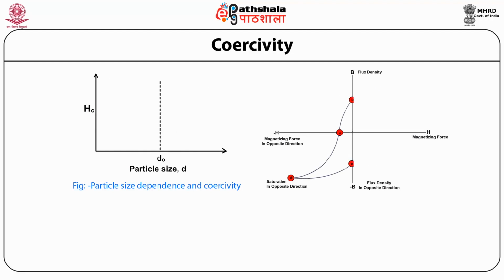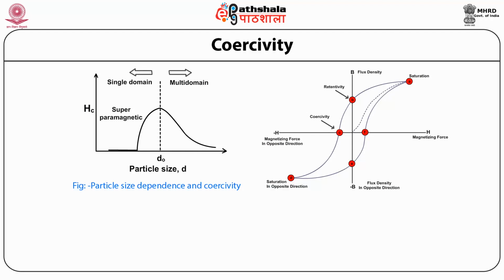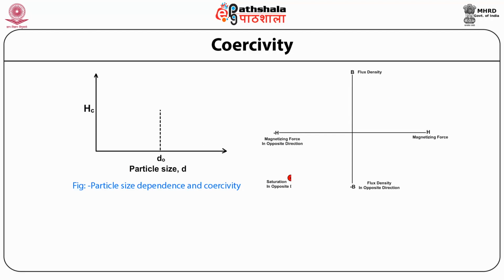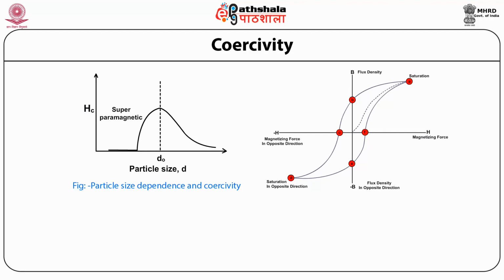This coercivity measures the resistance of a ferromagnetic material to becoming demagnetized. Coercivity is usually measured in oersted or ampere per meter and is denoted Hc. It can be measured using a BH analyzer or magnetometer.